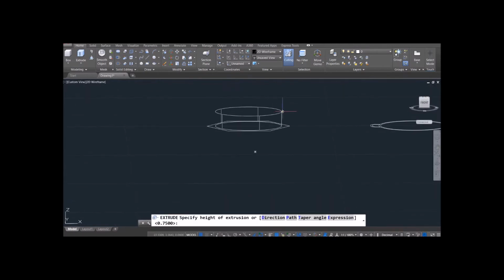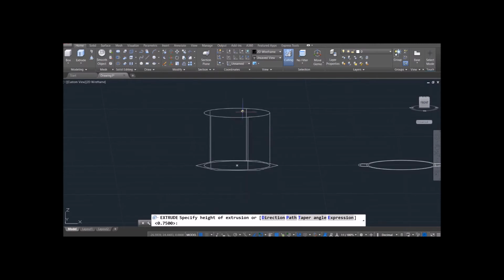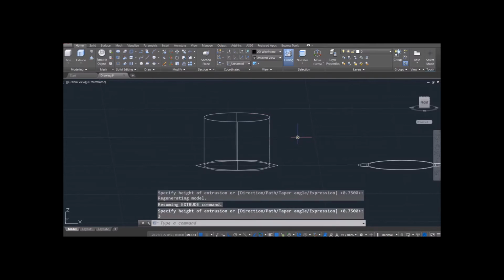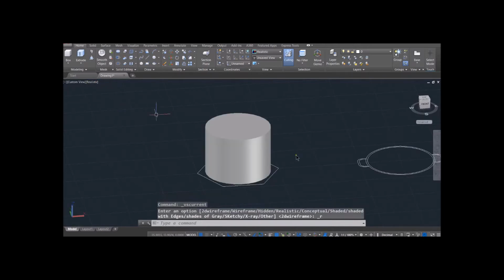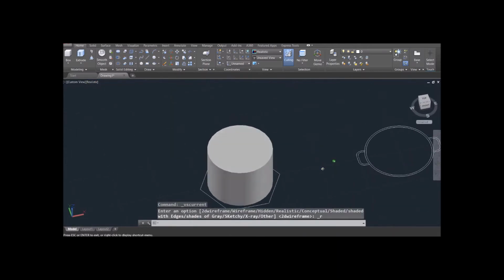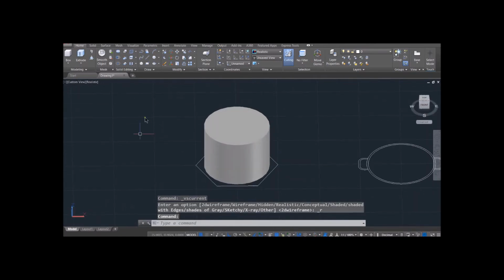Just tug it in the direction you want it to go in. So I'm rotating with shift key and pushing down on my rolling button. Get it going in the way that you want to extrude in, so it is extruding up. Also play around with your different views. Sometimes the solid view is a little bit more descriptive than that 2D wireframe.